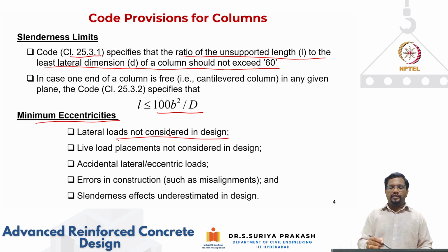And the second reason is, if the ratio of live load to dead load is high, then your live load placement also will play an important role. So the live load patterns have to be considered in demand estimations. If live load placements are not considered in design, then again it will lead to additional bending moments. To account for that, the code is saying that you need to consider some minimum level of eccentricity in your design.